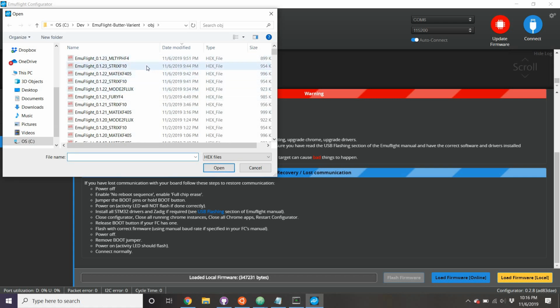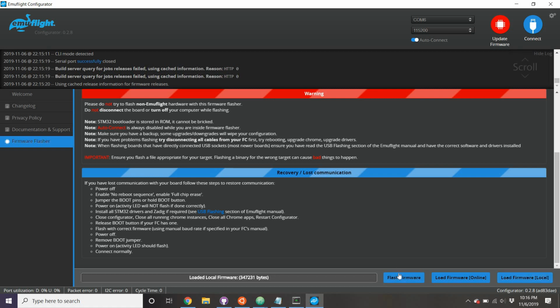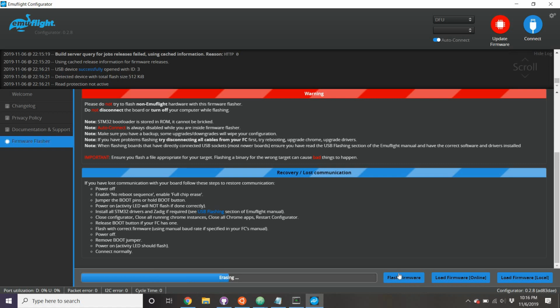Today I'll be covering those, but I'd like to start off by talking about this new version 0.1.23. Just to catch you up, this version includes the auto cell profile swapping, or whatever it's called, from Betaflight, which is where if you put in a 4-cell battery and then you put in a 5-cell battery, you can make the PIDs automatically change based on what voltage battery you're running.